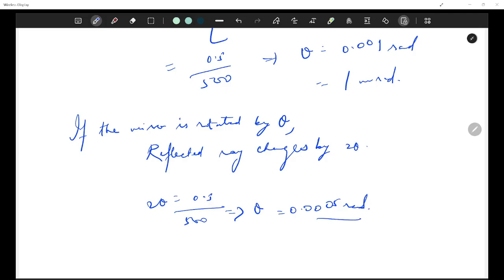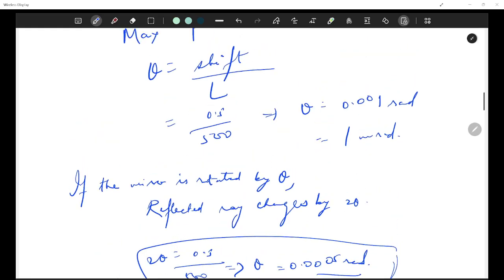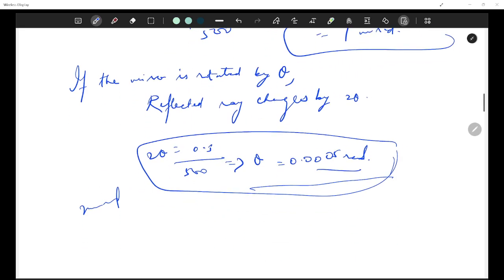Okay, but the practical derivation which is used in heliostat systems accounts for total image spread geometry and realistic tolerances. When calculated carefully using beam geometry and worst case conditions, the required pointing accuracy comes close to 2 milliradian. Okay, so from here, I guess we do not need to go for this, but we can go with this answer of 1 milliradian. Okay, this is actually not required.